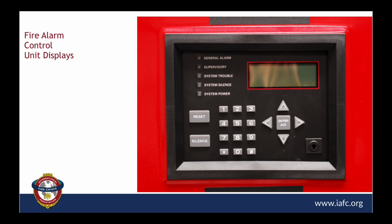Another area that this could show up on is your duct smoke detectors. The code today, for the most part, is pointing towards duct smoke detection to come in as a supervisory signal into the fire alarm control panel and be transmitted to your central station and to your dispatch office as a supervisory signal, so that when you walk in, it'll show up here as duct detector HVAC unit 12, serving floors 1 through 2, and give a location of where that device is located. Now, those first two are initiating alarms, letting you know where things have come from.